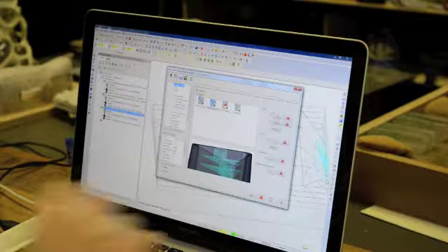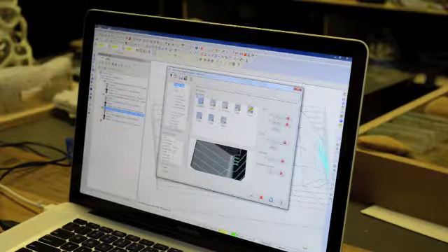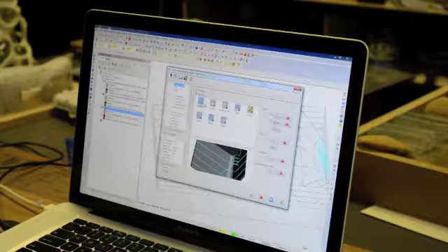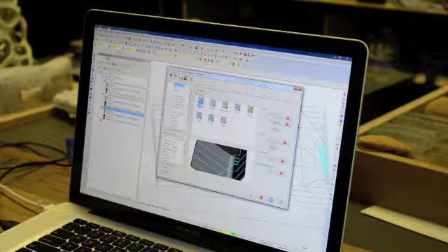So this time, we have 2 options from toolpath type. We're going to do a finish now, and you can see there's all these different options, so you can experiment with these, see what works best in terms of giving you the finish quality you want and the type of toolpath aesthetic if you want that to be part of it. For this, let's try a waterline.